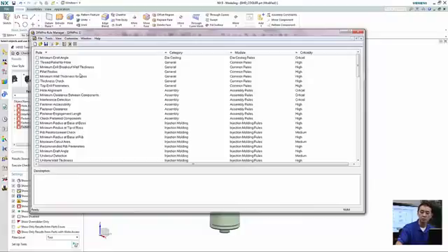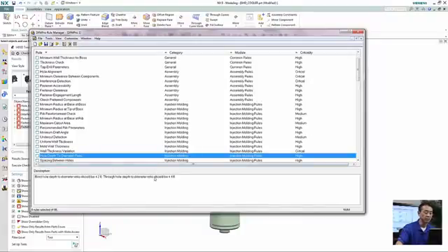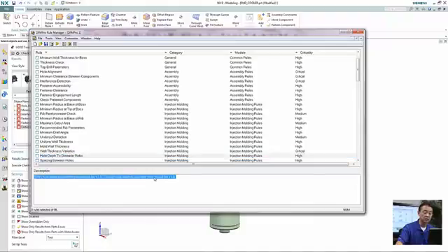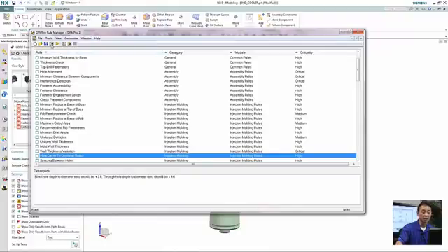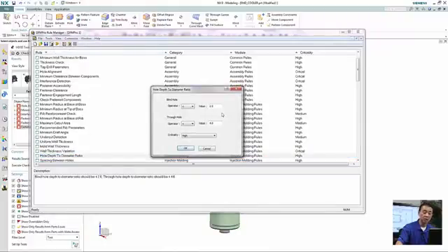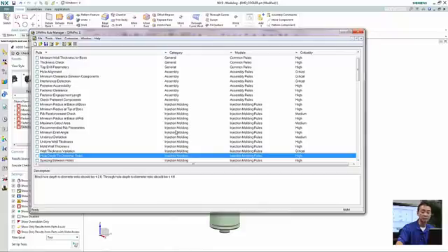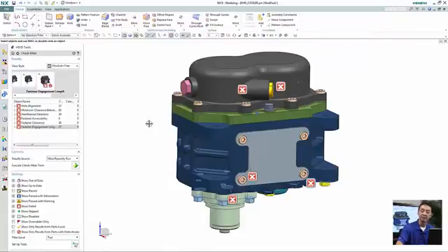Next, at the conclusion of this demonstration, let's take a look at some of the standard rules that come with design for manufacturing. We can take a look at just one, for example, the hole depth to the hole diameter, the L over D ratio. For this particular company, we set that to be no greater than 4. So we can actually change that. Sometimes for other designs or other factors and different areas of consideration, that value could change. So each company can set up their own standards using the rule managers. This is where they can come in, quickly make that modification, rerun their analysis and be able to get different results.